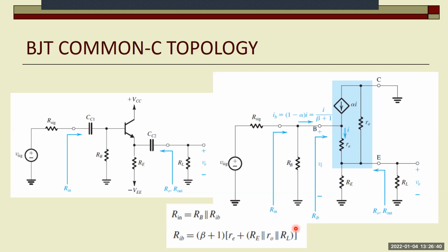So the total input resistance Rin is the base dividing resistors in parallel with that RIB. On the other hand, output resistance, I don't have to go through this, you remember, was the parallel equivalent of R0, RE, then that small re plus whatever is connected to the base divided by beta plus 1 or HFE plus 1.